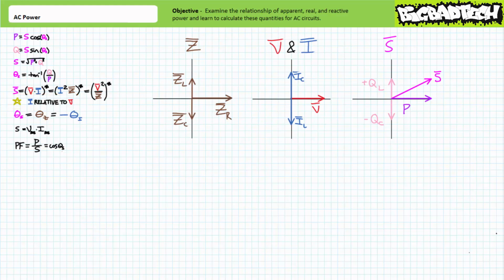While ordinarily this is the case, it's not always the truth, especially in larger circuit analysis scenarios where some other absolute reference might be employed. This important precondition often necessitates a student calculate the relative phase shift between voltage and current. Unfortunately, students are often in a rush and neglect to perform this most important step. Don't be that student and get a wrong answer every single time. Be that student that understands current must always be referenced with respect to voltage for the purposes of AC power calculation. In summary, absolute phase shift is of little concern, whereas relative phase shift is of prime importance for AC power calculation.